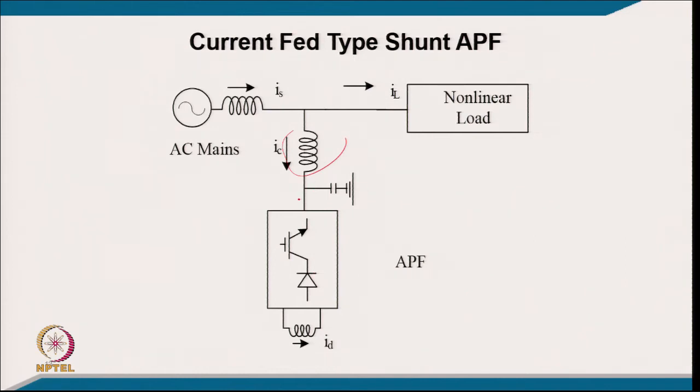Moreover, the shunt capacitor, because these are PWM current segments of the DC link current, is needed to make this current continuous, typically because the switching frequency is quite high. So, this capacitor is mandatory; that is an additional component in the case of a current source. So, you have more losses, higher cost, bulkier size, and more components. That is the reason.